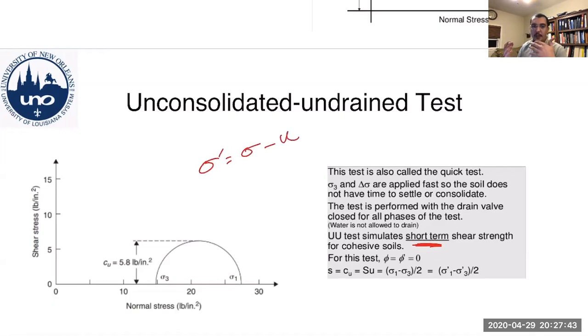So you would have a drained condition, meaning that as soon as you apply the load, the pore water pressures dissipate or leave the sample. An undrained condition means that there's a lag time, so with the application of a vertical effective stress, you don't have water leaving the sample at the rate that you're applying the stress.